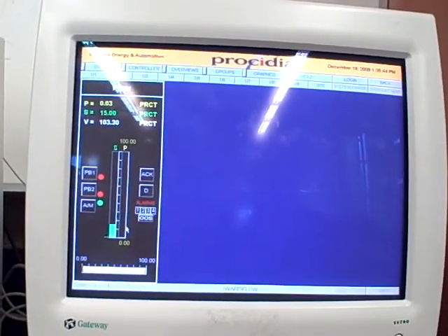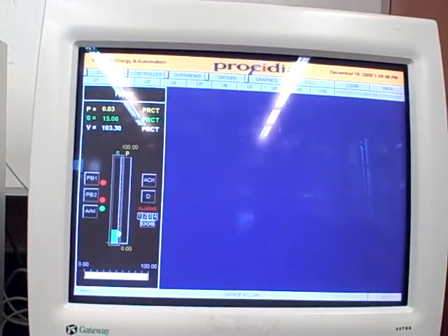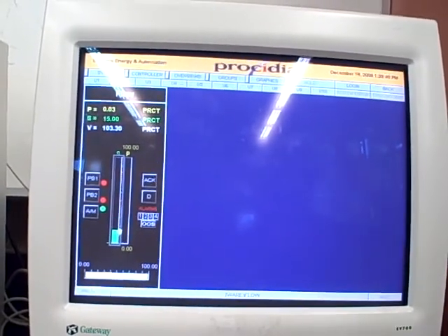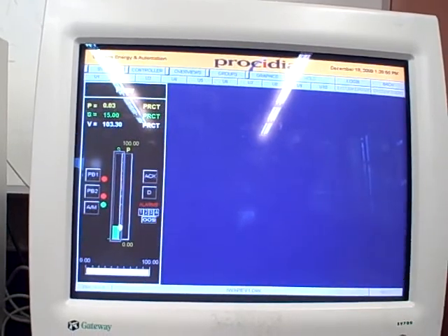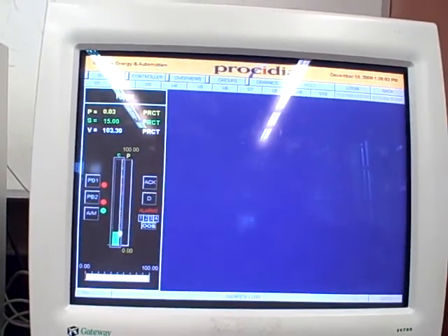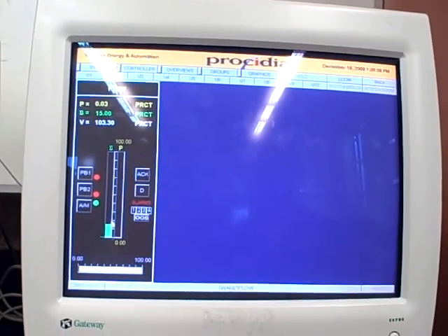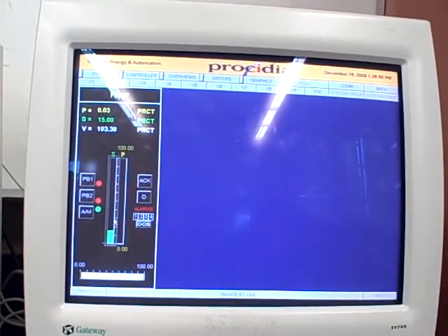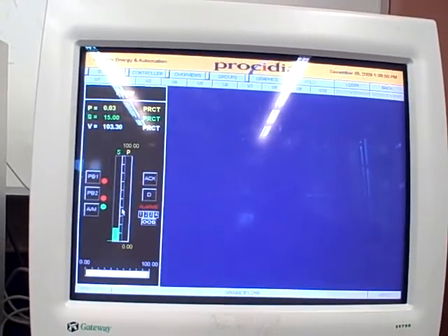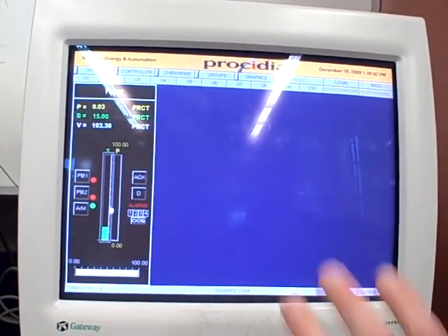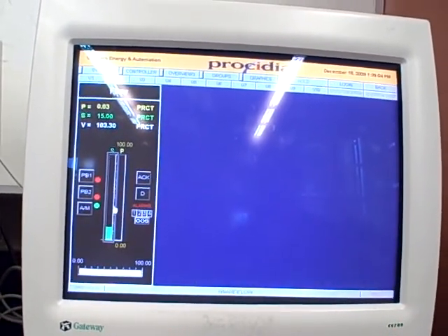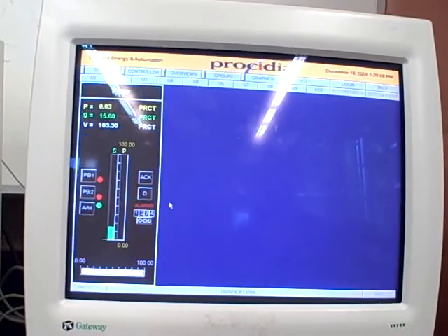This is all happening through an OPC data exchange network. OPC is a standard based on Microsoft OLE technology for linking and sharing data between different hardware devices or between applications on a single computer. In this case, I'm using the data exchange format to send data back and forth between this personal computer and the 3 Siemens Model 353 controllers.